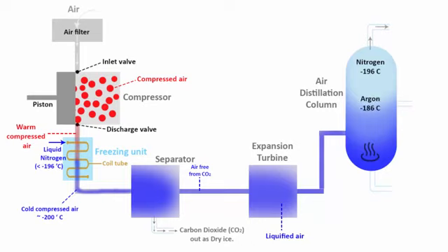After that, argon gets separated, because argon boils at -186 degrees Celsius. Oxygen, which has a higher boiling point, is left behind and is collected separately. Now please don't get confused, because -196 is much cooler than -186. Oxygen boils around -182 to -185. So if you look at these three temperatures, obviously -185 is higher compared to the other two. That means oxygen has a higher boiling point. At the bottom of the air distillation column, you will see liquid oxygen settles down.